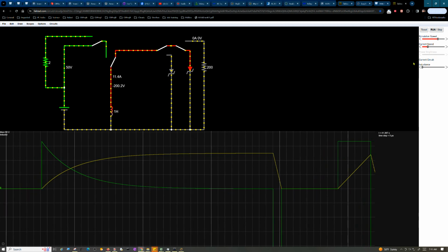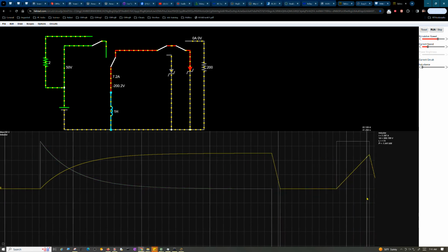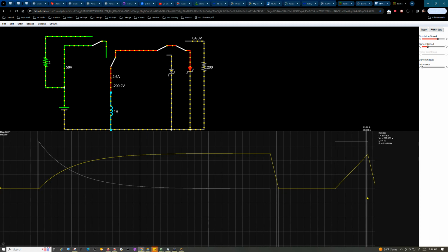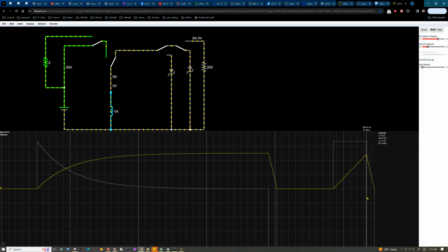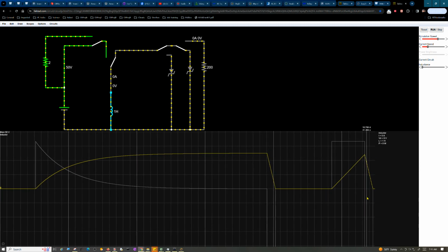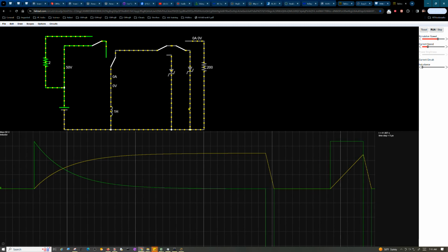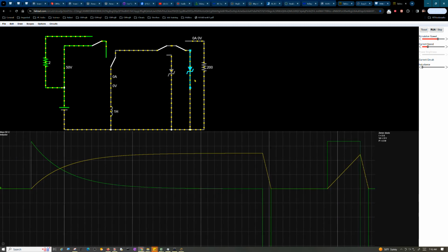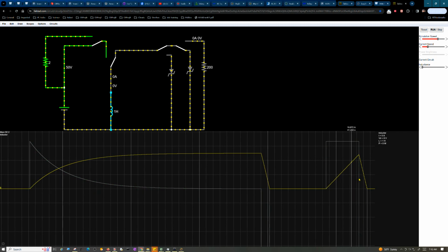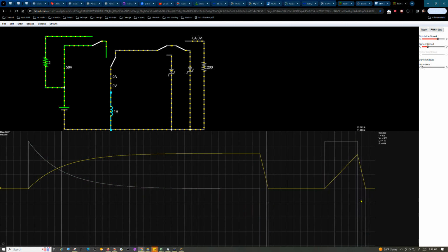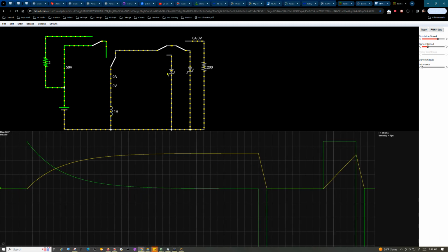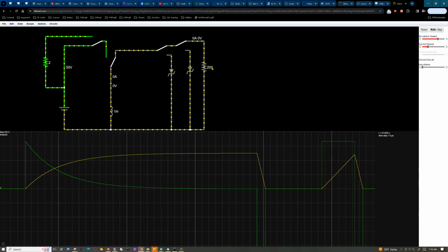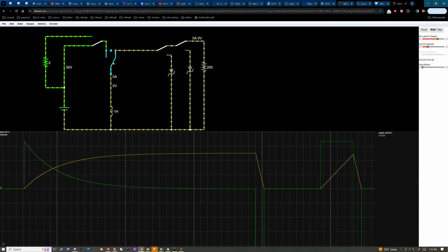Its magnetic field. It's linearly discharging, because again, in a real world coil, it wouldn't work this way exactly, but you can come close, if you had sufficiently low resistance and so forth. But at any rate, the fact of the matter is that it discharged at a much higher voltage, but very quickly. Alright, now let's switch it over to a 200 ohm resistor, and let's see what that does.